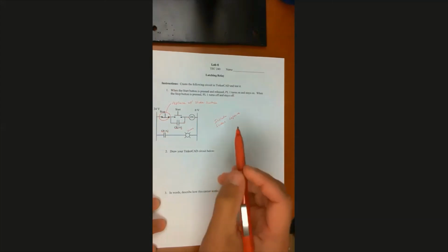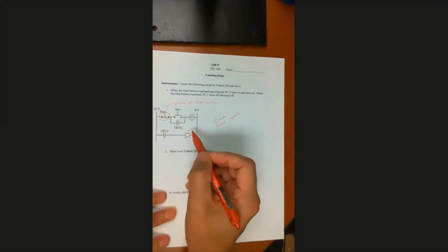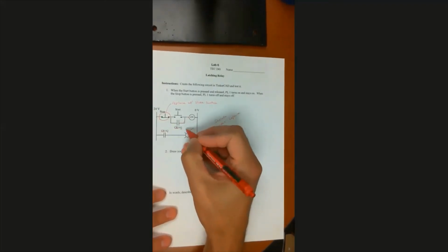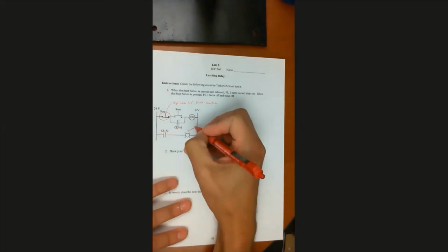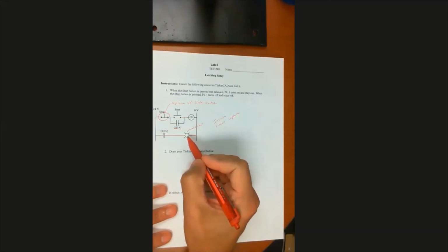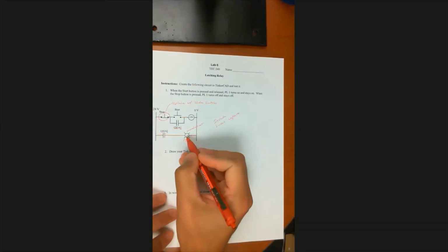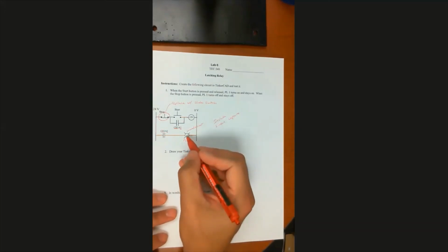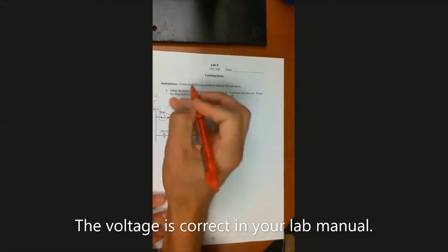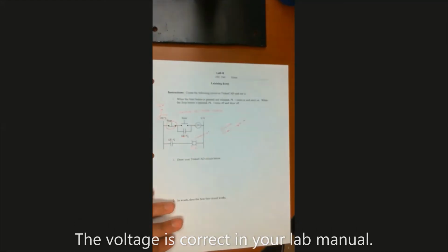Okay. Make sure you include your screen capture at the end after you've built it and tested it, and make sure it works. And then this is the note I was making to remind myself to discuss that when you put this light in here, it's a pilot light, call it PL1 or something. Use the incandescent, and to make sure that that works, change this to 12 volts. All right, so make sure you change that to 12 volts and change that to a slide switch.